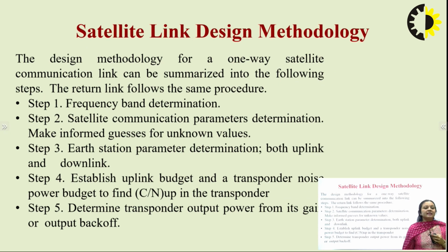Now, satellite link design methodology. The design methodology for a one-way satellite communication link can be summarized in the following steps. For establishing the second link, that is from the satellite to the earth station, you can again repeat the same process. The return link follows the same procedure. So my step 1: frequency band determination. First select the band in which you want your satellite to operate. You want to operate it in C band, L band, or whichever band you want.